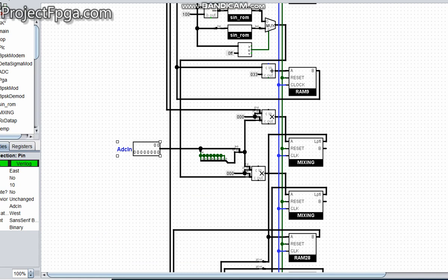That is, the MSB is extended. It's a total of 10 bits, but the MSB will be extended to make it a total of 18 bits. This is how I extended it: I added extra 8 bits at the beginning, and they took the value of the MSB.